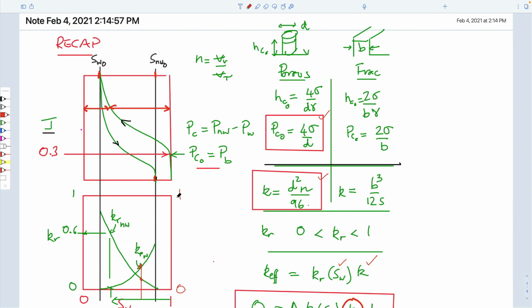We then went on to talk about the movement of fluids and defined that in terms of breaking Darcy's law up into two parallel pipes, if you like, where the relative transmission of the two phases scales with their saturation proportion. We could draw these X plots which define the relative permeabilities. And we also rationalized that they shouldn't be X plots, they should be truncated X plots, which should go here and here and here, if anything, to be able to describe this behavior.